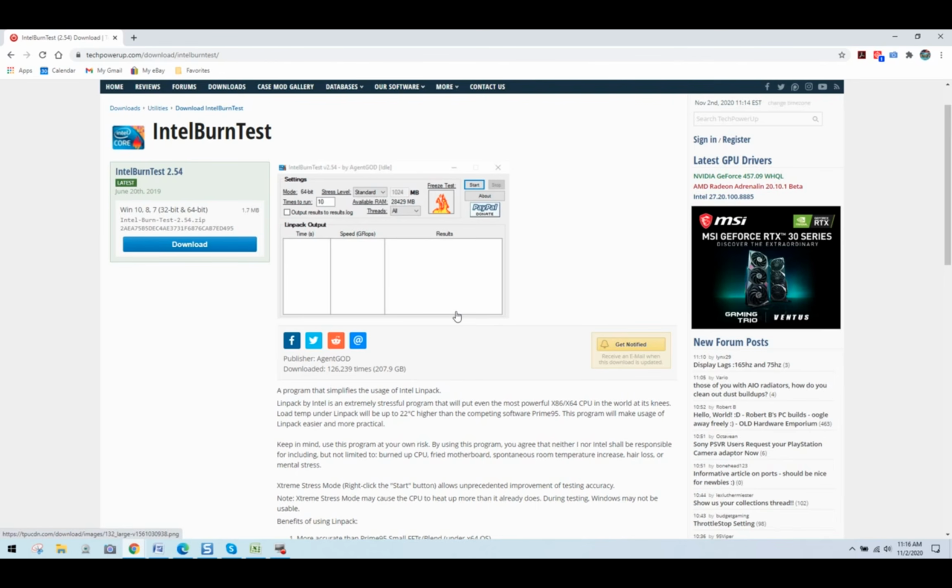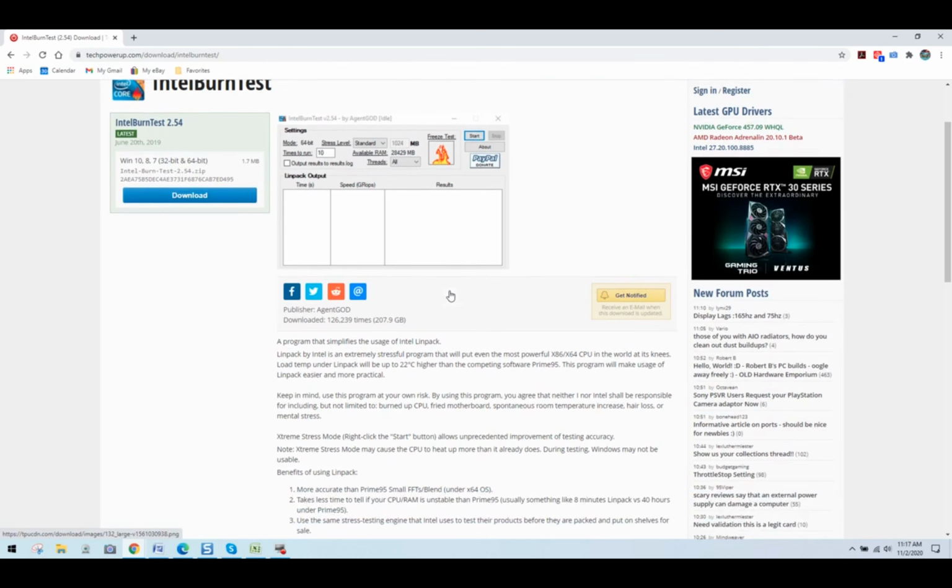Okay, we are dealing with a machine that is a robot. It is not a machine that's designed as a drill press, as a scroll saw. This is a robot. So again, when I hear guys contact me and tell me about steppers are hot and this is hot, of course they're going to get hot naturally, but when they're in another 100+ degree ambient temperature, how much hotter are they? How come parts fail prematurely? That's why.